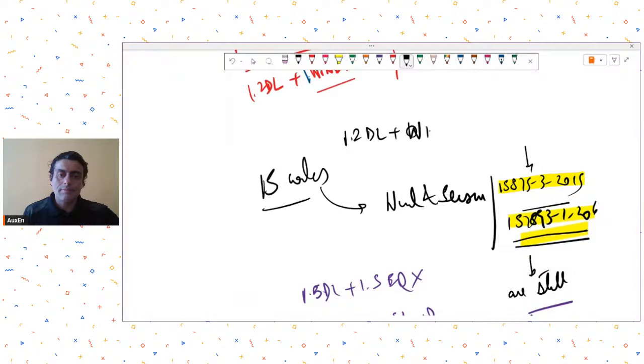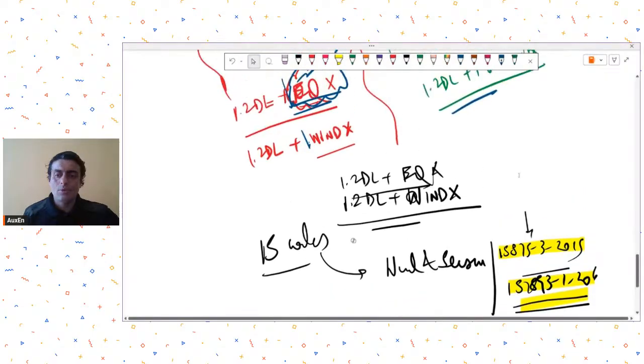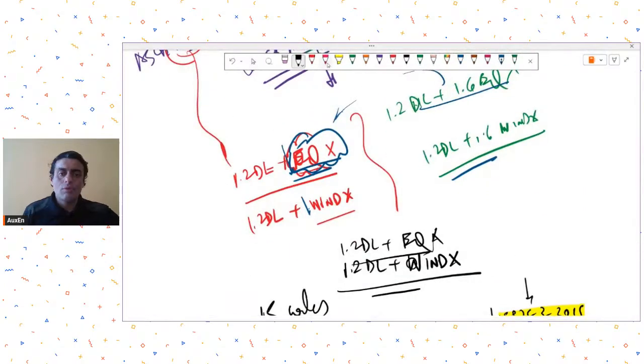Do you understand? They will use the load combinations from the AISC or ASCE standard. So this is a big mistake. Why? Because you are using lesser values of wind and seismic. If you want equivalence, then you should have used the load combinations that were given to you before ASCE 7-10.